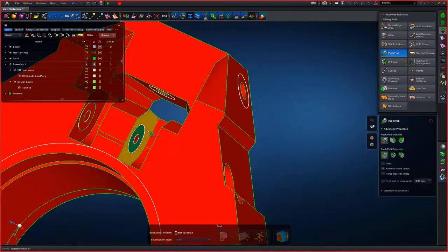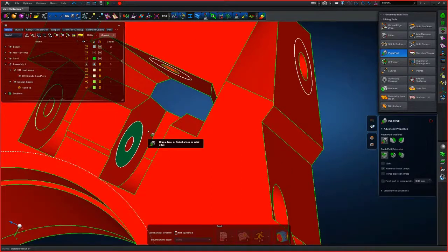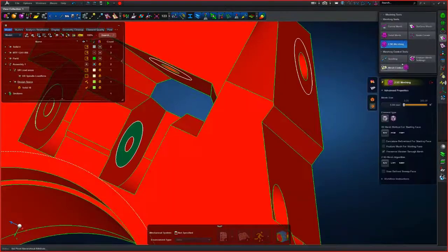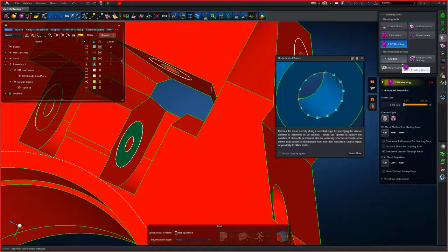Delete the mesh. Remember all your boundary conditions and loads that you've applied, even mesh seeds, all those things will remain. So by deleting the mesh, you remove the requirement for anything to update, and you can do all the CAD modifications very quickly that you want, and then you simply just remesh it with the properties that you wanted in the first place. So that's at this stage the workaround for that, and that's especially useful when it's a very large model that takes a while to remesh.